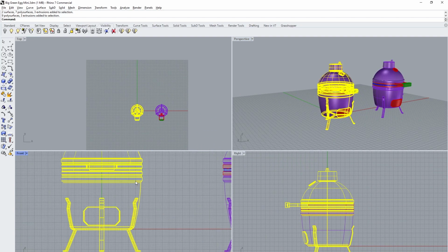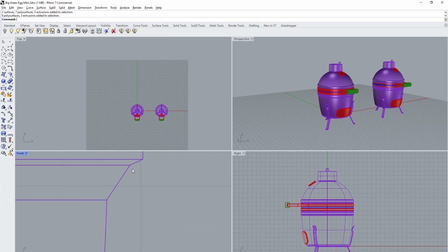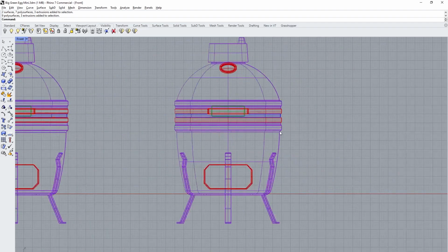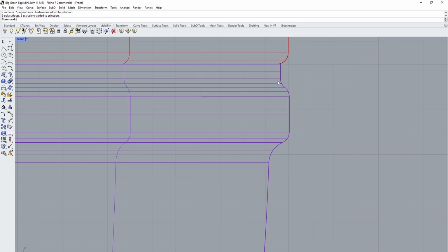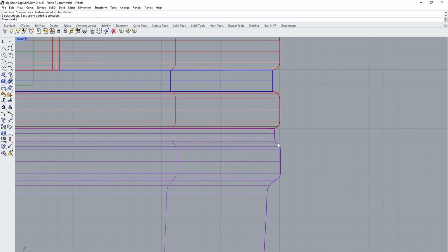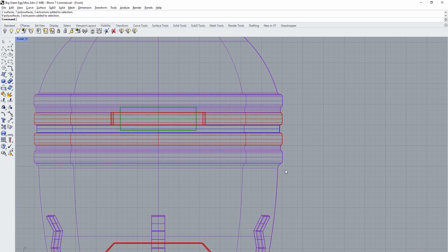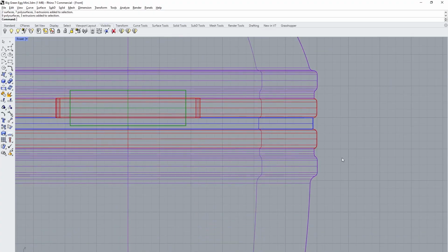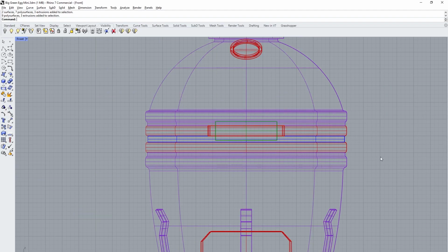This one that has been importing well, if you look at the corners here, has some corners that I've put in instead of the rounded objects. You can see here we have nice smooth objects. But these radii here, I think, are 1/8 of an inch. And this is not a scientific analysis, but it's just something I've meted out through hours of work on this thing: when you start getting down to radii in the 1/8 of an inch range, I've found that Revit starts to drop them or just glitch out on them.